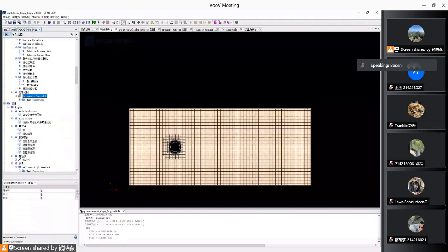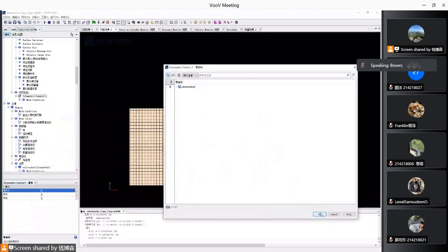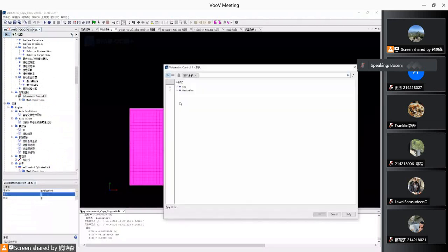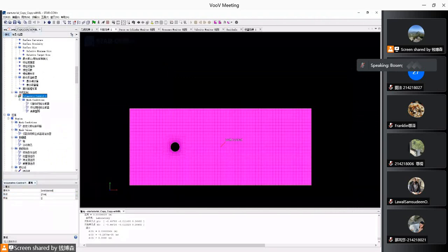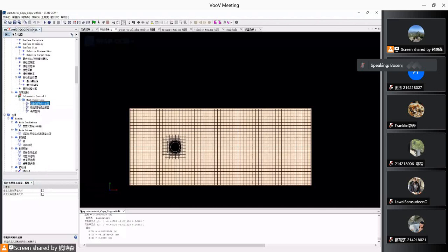Okay, so where was it? So the part, we need to select the part and select the shape. Let's start with the fine region, and let's set up the mesh condition. Select the isotropic size, custom size, relative size. So what would the spatial resolution be?